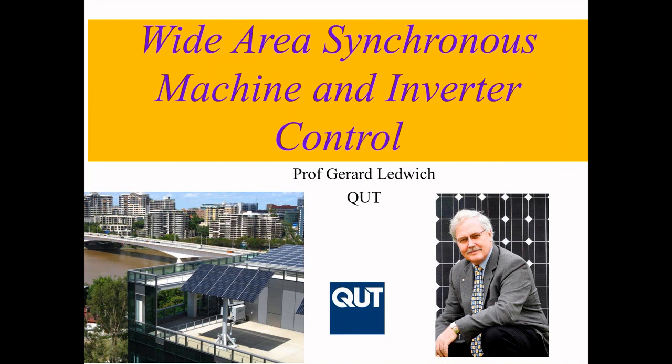It's also a problem for protection. So for phase lock loop stability, I believe the solution is Kalman filters to infer a stiffer point or broadcast angles. For protection purposes, I am saying that we're starting to need a different philosophy of protection that says even if we've got inverter supports and that reduces fault currents, that does not mean that we cannot distinguish faults. But there's more work needed in that domain to make sure that the weak grid scenario is not such a boogeyman as it is at the moment.